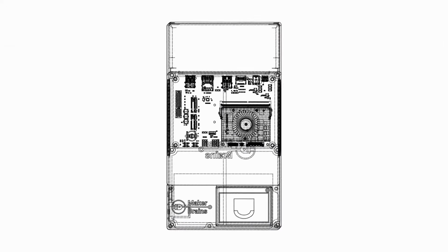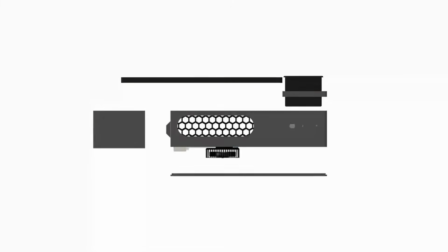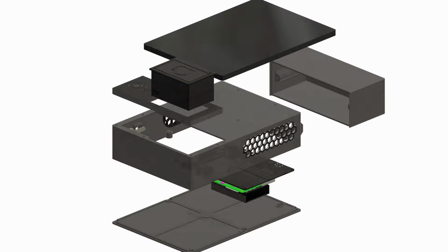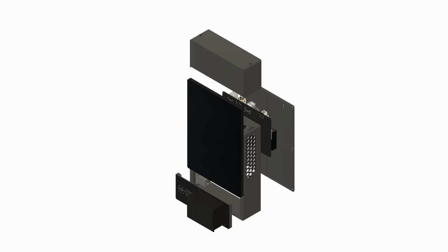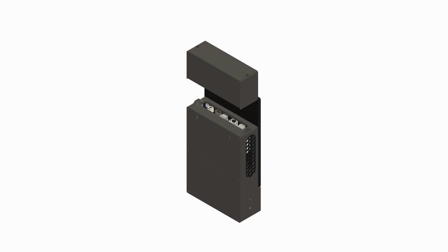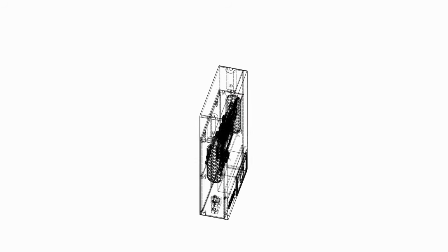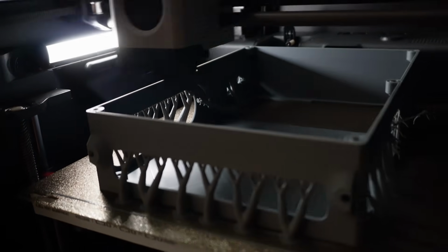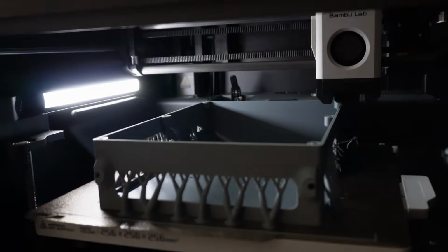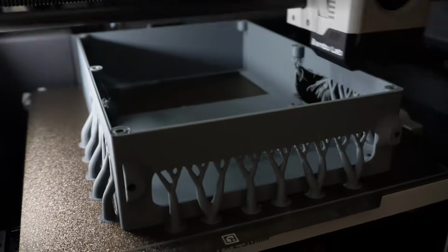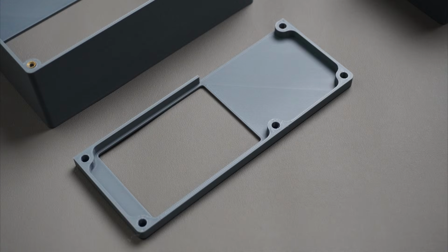To begin with the build, I designed the custom enclosure for Open Kiosk using Fusion 360 to ensure a compact, modular, and professional look. I started by importing official CAD models for components like the Latte Panda Mu. For the parts without available models like the thermal printer, I measured the dimensions manually and designed the 3D model. Once all components were modeled, I began designing the enclosure to precisely house each part. I 3D printed all these parts on my Bambu Lab P1S in grey colored PLA. The design supports metal heat inserts so each part can be assembled using standard M2 and M3 screws.